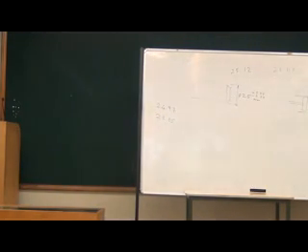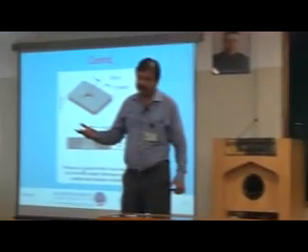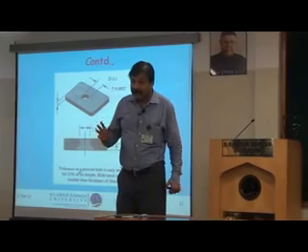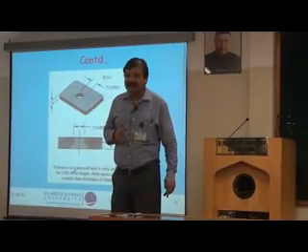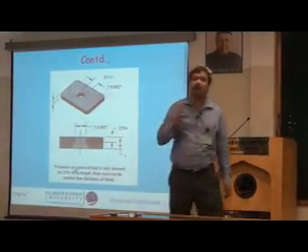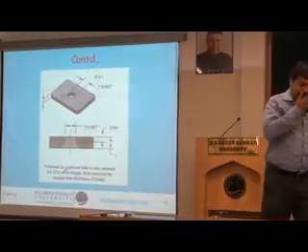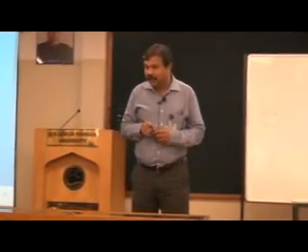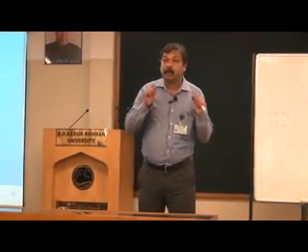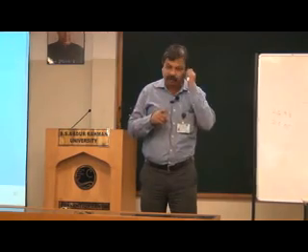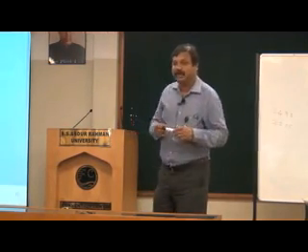Now for pressed components, it is preferable to give as large a tolerance as possible. Generally, any designer must resist the temptation to reduce the tolerance. In any good design, you must provide as large a tolerance as possible.